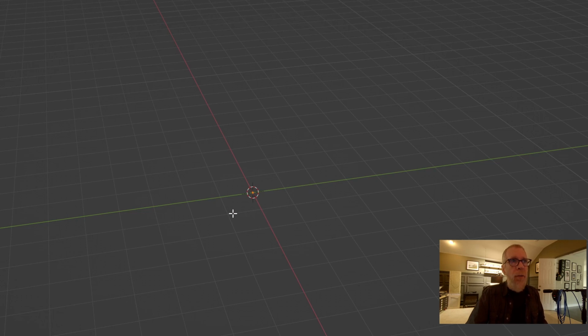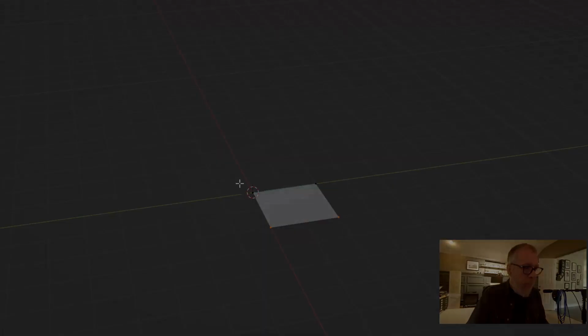And when I do functional models, I use this all the time. This way I can extrude it specific dimensions, say, I don't know, 2 millimeters. I just typed in 2 on my keyboard and it brought that out. I can then go and extrude this, say another 2 millimeters. So I can do things like that. So I tend to use this quite a bit.